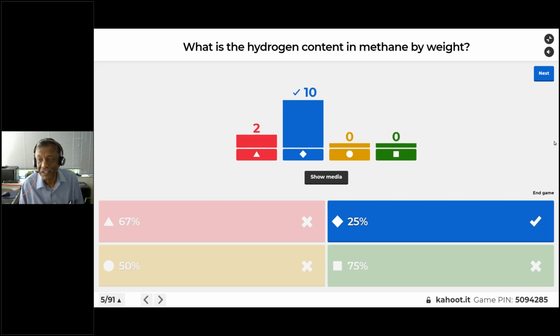And it is this carbon which we are concerned about. We are concerned about carbon dioxide, the greenhouse gas emission, because whenever we are manufacturing hydrogen, we will have this unnecessary baggage which we don't want, in the form of carbon dioxide, carbon monoxide, methane, all these greenhouse gas emissions. So we have a very tough task ahead of us: how to produce hydrogen using steam reforming and at the same time take care of carbon. Where is all this carbon dioxide going to go, actually? 75% of methane is carbon content, and when it combines with oxygen, the mass goes even higher.